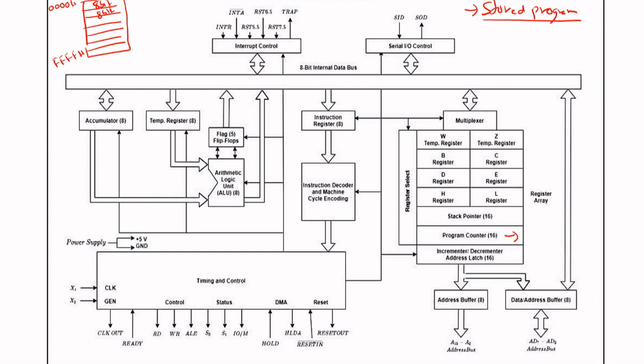Okay, so the program counter, as I told you, contains these particular addresses of a particular instruction that is supposed to be fetched for execution. Now, the 16-bit address is divided into two parts, basically the most significant 8 bits and least significant 8 bits, and then multiplex data and address bus. The address bus as well as the multiplex data and address bus are used to point to a certain memory location from where the instruction is supposed to be fetched.